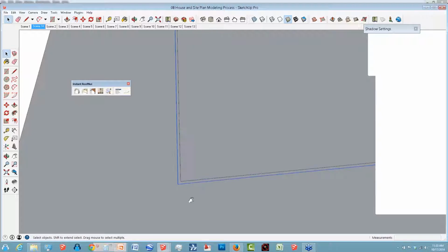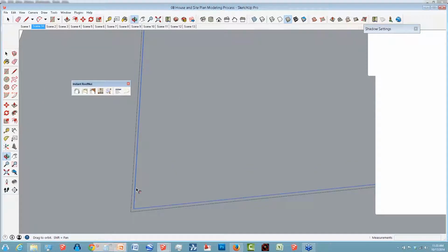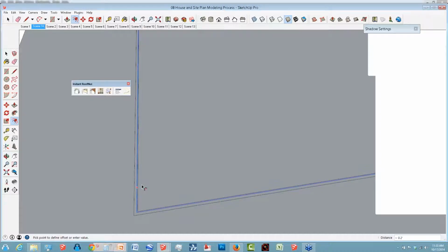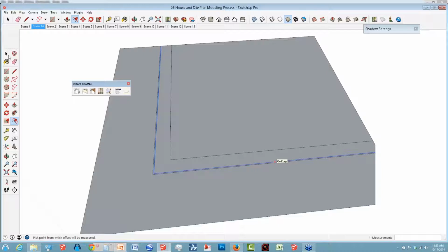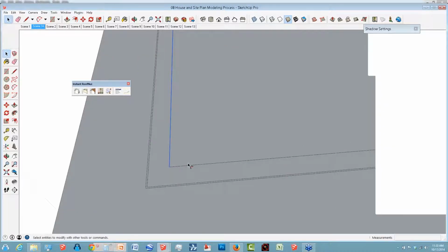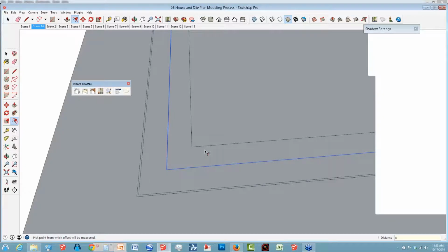Boundaries for areas. I'm going to select those edges again, and now I'm going to add an 8-foot tree lawn. So I'm using the offset tool with the selected edges. At the bottom right, I simply start typing the distance I want it to offset. It offsets at 8 feet, and there's going to be my tree lawn. I'm going to select those edges again, take the offset tool, and offset these out another 8 feet, and that's my walk. So there's my first part of what I'm trying to do here.